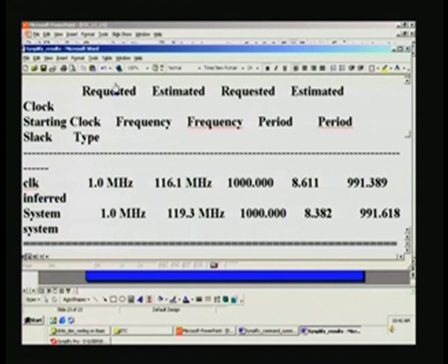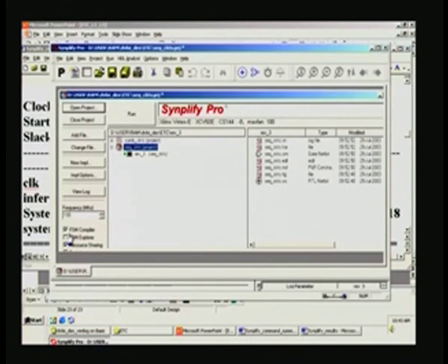What the requested frequency is, what is the frequency here? I think I forgot to put the clock frequency there. So by default it was 0 there, right. In the Simplify window, we are supposed to put 100 here. I made an entry of 100 only subsequently. Earlier I had forgotten, it was just 0.